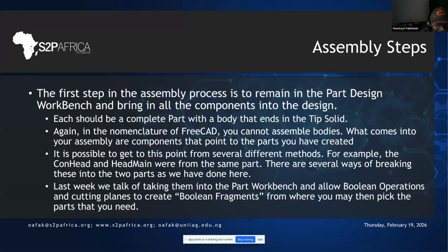Assembly steps. The first step in the assembly process is to remain in the Part Design workbench and bring all the components into the design. Actually, it is all the parts you are bringing into the design. But there is confusion even in the way FreeCAD talks about parts and components.